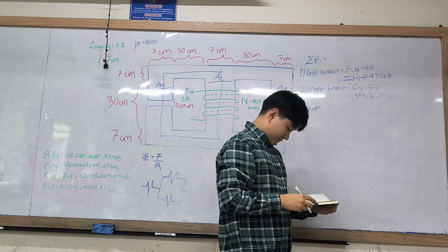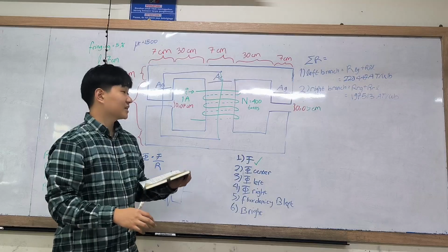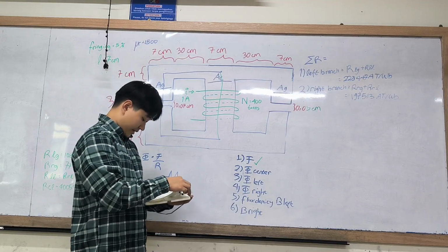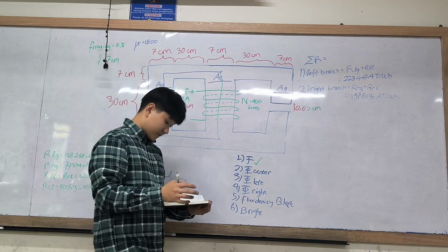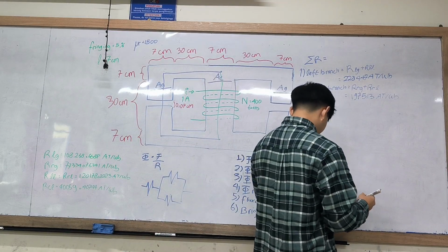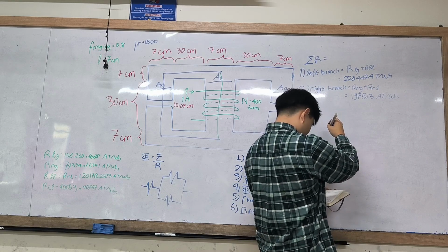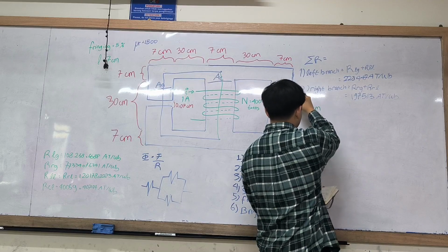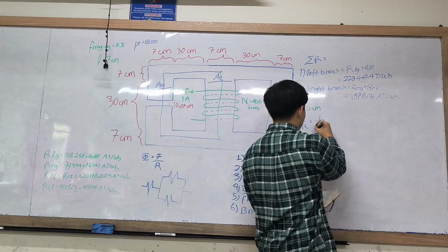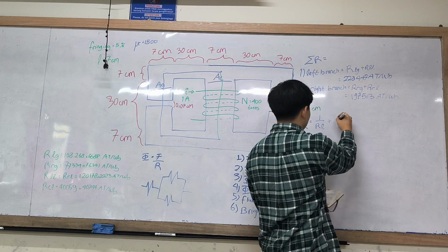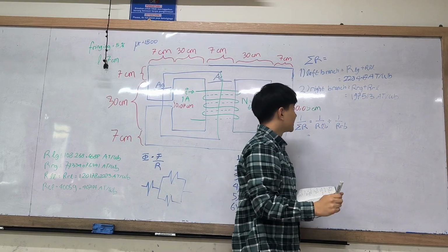And due to their parallel nature, when they are combined, they cannot be simply added. They must use the two resistors parallel formula when trying to be merged. So it is like this. One per total R equals 1 per R left plus 1 per R right, because it is a branch.